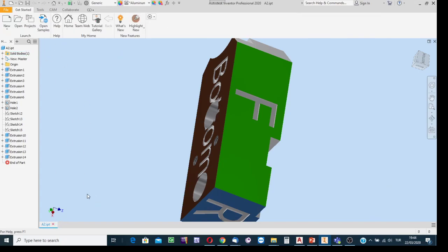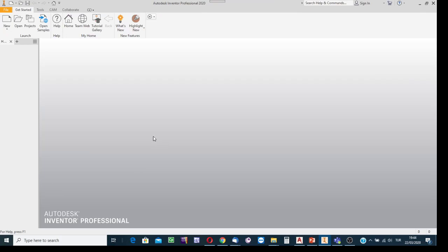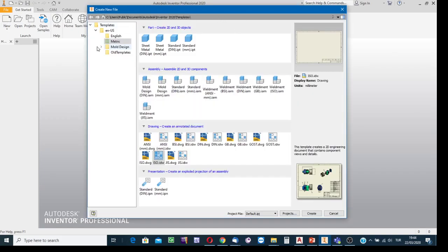Okay, I open Inventor and say that the solid model is available, either on the screen or in the memory of the computer. If it is time to create the views, then in Inventor, since it is going to be a new file in this logic, click on the New File Creation button first. And in the dialog box, select from this list.